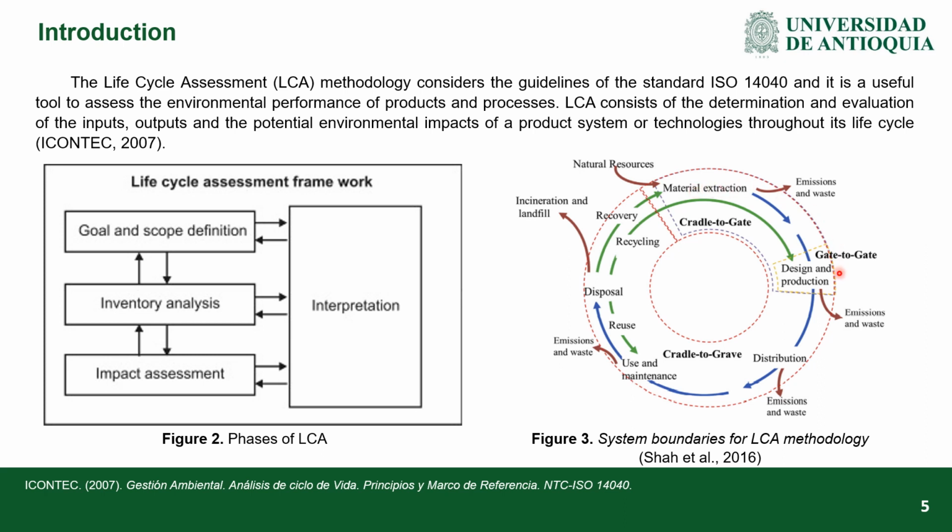Cradle to gate considers from material extraction to the factory gate. Cradle to grave is the complete LCA from material extraction through production process, distribution, use, and final disposal stage, including related transport. And cradle to cradle considers the complete LCA and admits the recovery and recycling of the outputs of the waste disposal of the system.